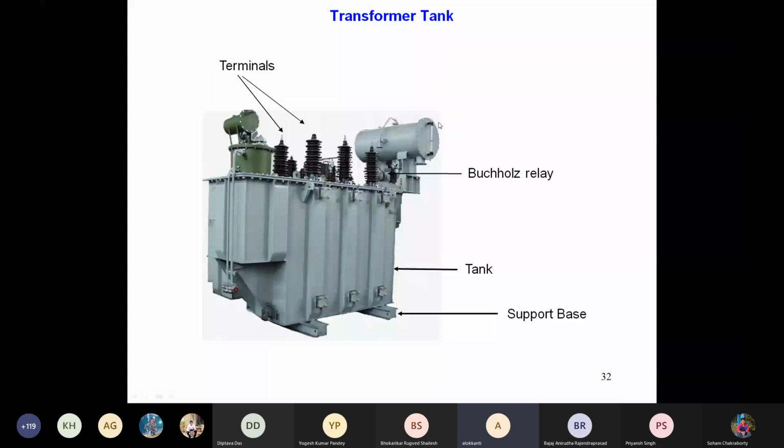Through the breathers, there are some balls, I forgot the name, which can absorb moisture, because you cannot get this oil exposed to the atmosphere or a moist atmosphere. Once this oil gets heated, it basically vaporizes, and there is a safety arrangement which is called the Buchholz relay,